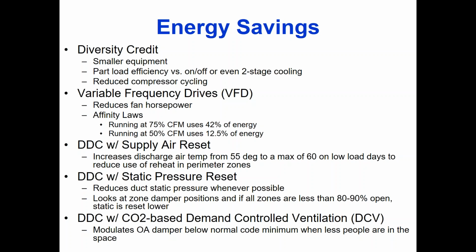That's a whole other topic in and of itself, but that can be applied to VAV. It's a little bit different. I do need to have CO2 sensors on each damper, or at least on the dampers that are most representative. And then I can use an equation from ASHRAE 62 called equation 6.1 to mathematically calculate the other zones. I never ever do it that way. I always put one sensor on per damper. It is by far the easiest way to do that.